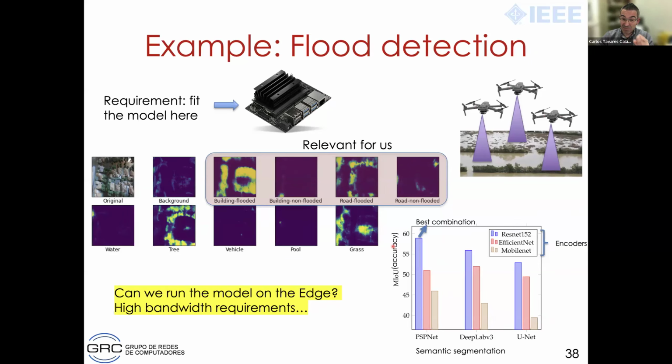Then some of these specific types of communication channels, like the telemetry. The telemetry is very poorly protected nowadays, especially, for example, using this Pixhawk flight controller I was showing you. They all have the same type of telemetry devices, and it's very easy to break in. Extremely easy to break in. And once you break in, not only can you read exactly where the UAV is and what it's doing, but you can send commands to change orders and change the mission. So not much protection there.